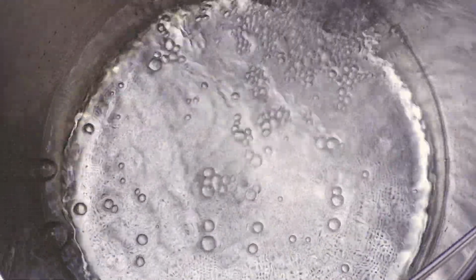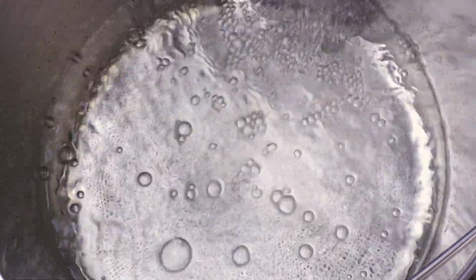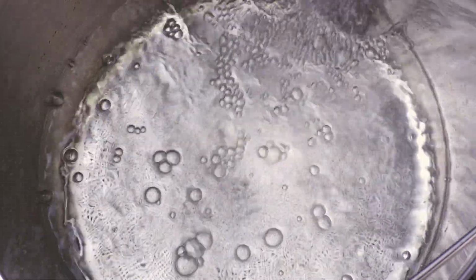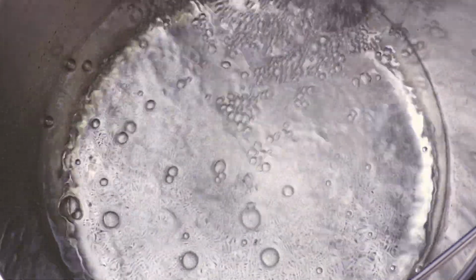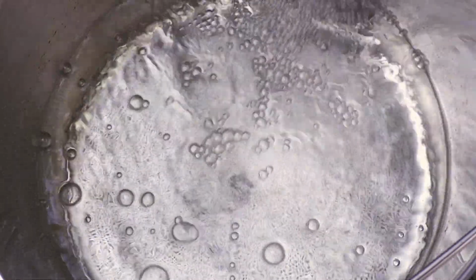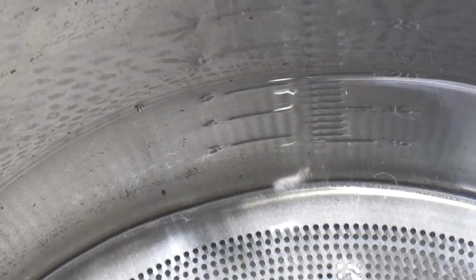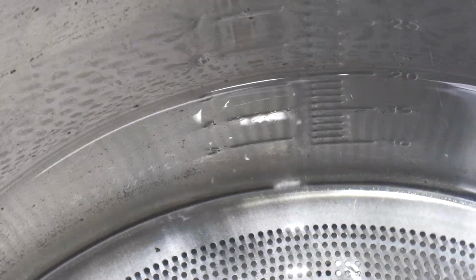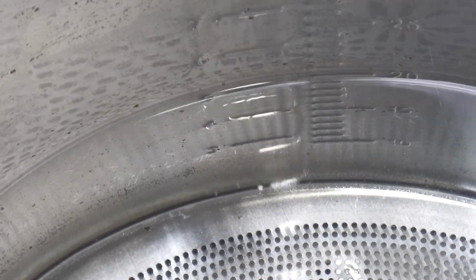Firstly, add a common mash-in volume of water for your brewing into your system. This can be a mean average if you like, as long as it isn't super wide. To determine this for myself, I looked over my most recent recipes and went for 20 litres, and this was on the basis that I generally brew 1 keg batches. However, if you're someone who brews 1 keg and 2 batches for example, then you will need to do this test twice. You will then need to take note of the best settings for each and swap over as you brew.